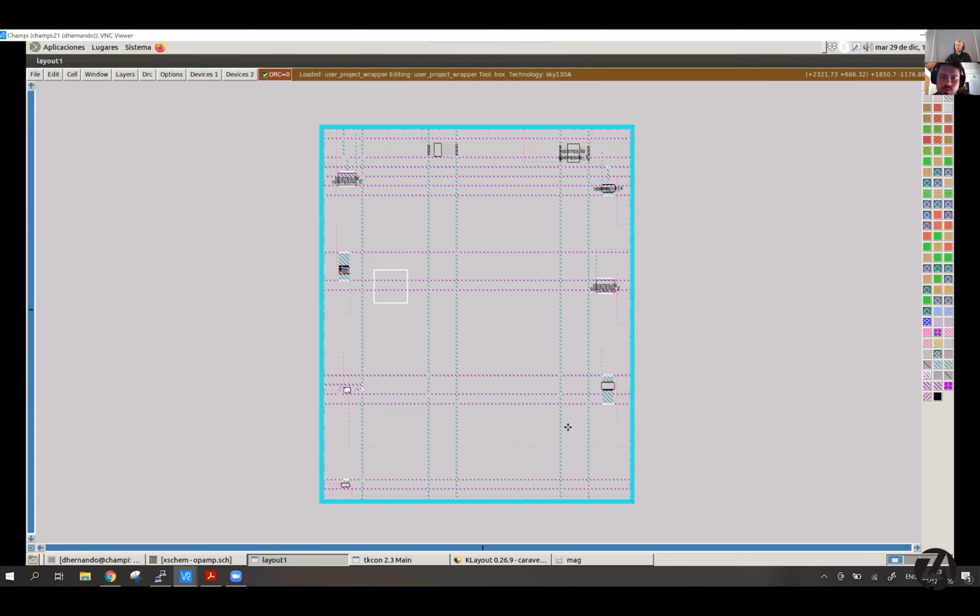What I have to do is that because I need to use analog signals into Caravel, I mean, the connection between the Caravel path and the user project wrapper needs to be an analog path, not a digital one. I have to change some routing in the Caravel design to make sure that I can use the analog path. Okay. I thought those analog pins were exposed as part of the user project wrapper.